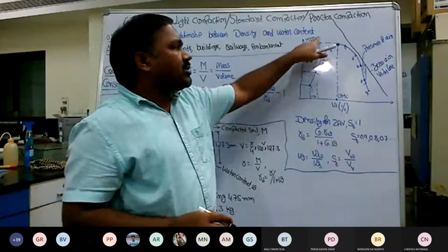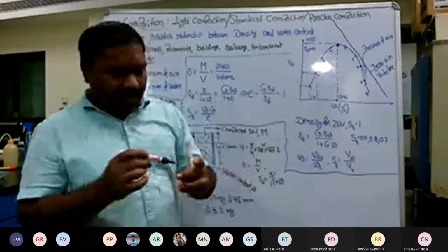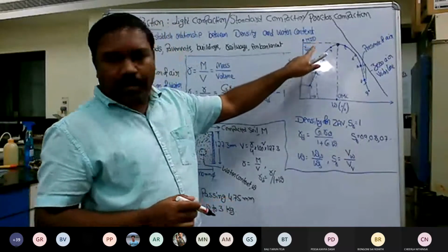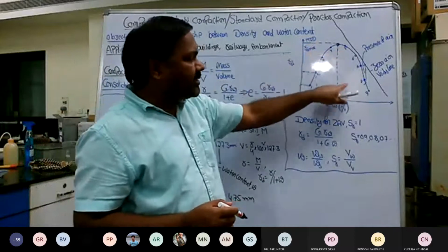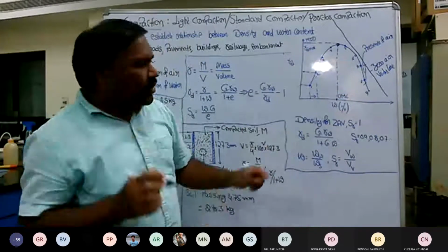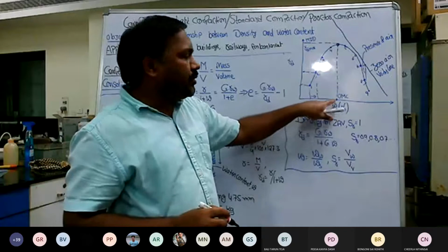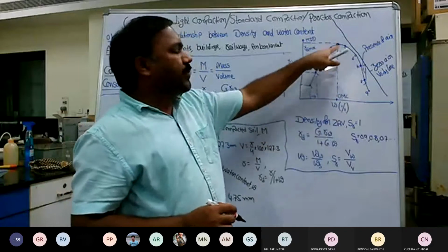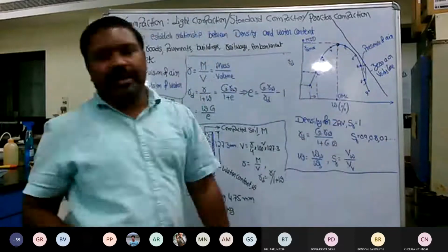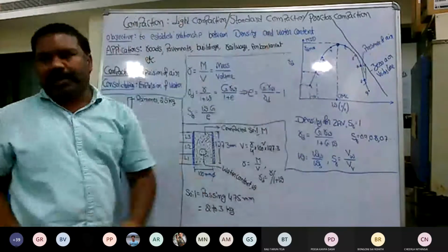Both are the same. In some of the books it might be referred to as maximum dry density, while in other books they might designate it as gamma D max, and corresponding to MDD or gamma D max, whatever the water content is, that is called the optimum moisture content. On the x-axis you are seeing the water content, but if you pick a particular water content where the density is at a peak, that is called the optimum moisture content. Beyond the peak there is a decrement in the density. And there is also something called a zero air void line that I will explain later.